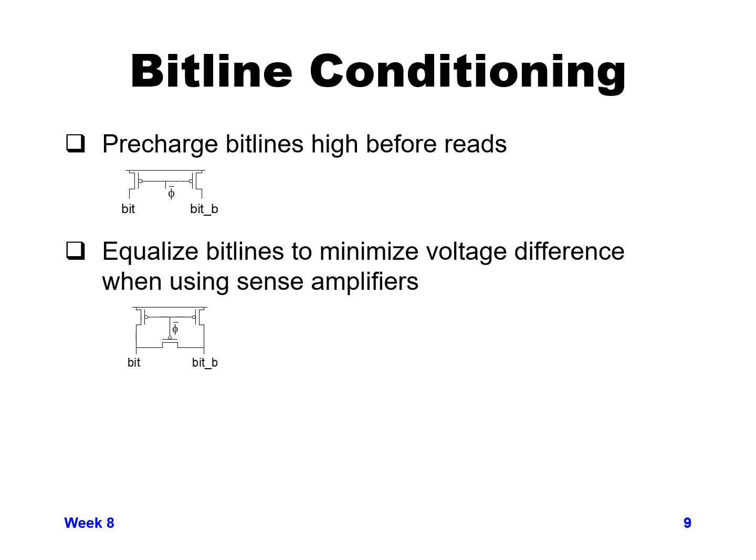If it's a clock bar going in there, when the clock is high, clock bar is low. But when the actual gates of the PMOS pre-charge devices are low, the bit line and bit bar will be pre-charged.